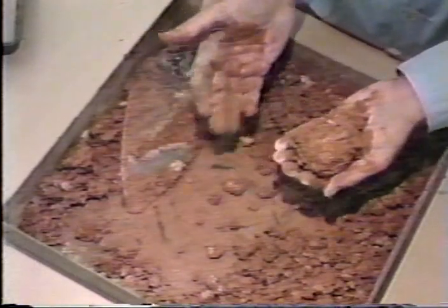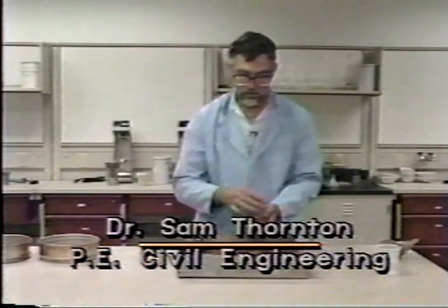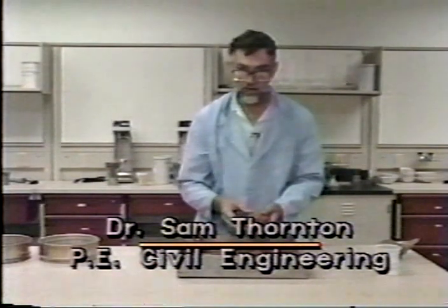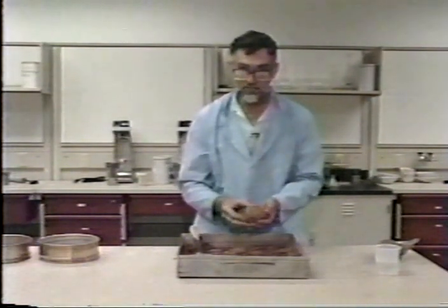Now, when this is compacted and dried, it will make a fine wearing course. All of the coarse aggregates will be stuck together. And this is what you want. You want not just gravel, which can be washed away with rain and the action of the people's tires and thrown to the side of the road. You want it to set up and make a strong, cohesive wearing surface.